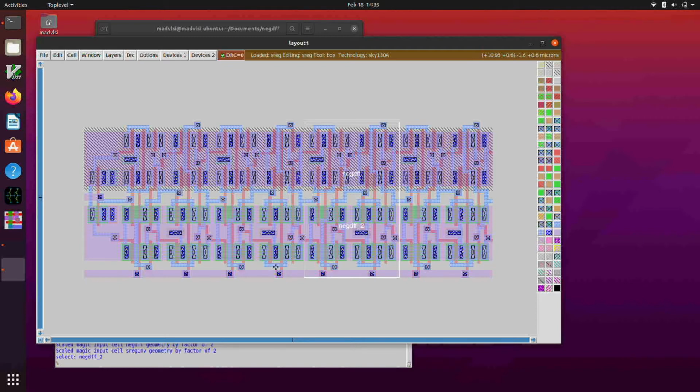And you can do this incrementally. You can figure it out beforehand and then put the box where you want the lower left-hand corner to be, and then go colon get cell to actually get the cell instance in place. You can also move the cell instance around by selecting the cell and then doing colon move, west 1, if you need to fine tune it.